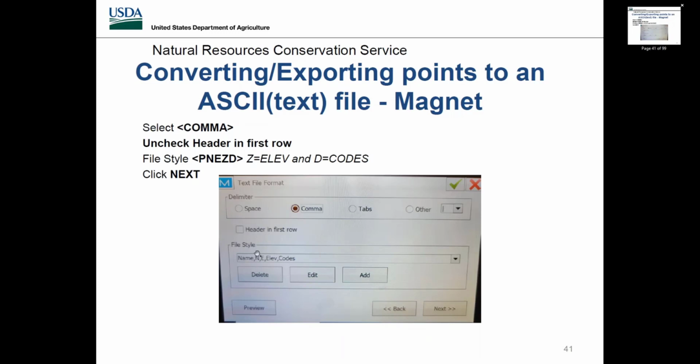Yes. I don't know if it works for ours, but I know for the national template Civil 3D stuff, if you put name as opposed to point, it'll let you put numbers and letters, alphanumeric, in there. So if you're transferring stuff over and you seem to have lost some points, just make sure that you're putting in the right style, because you could have accidentally put a letter in with your point number, and then it'll just disappear if you don't use the right style.